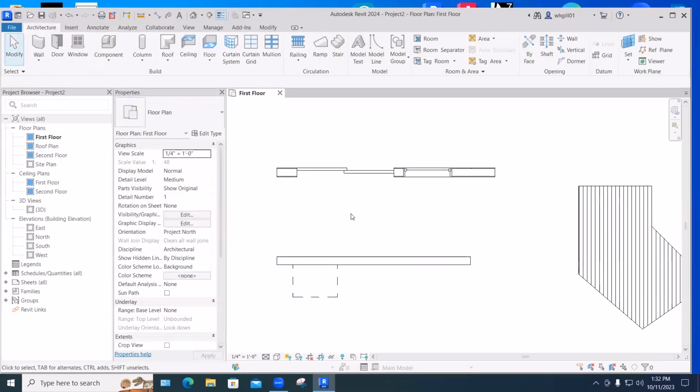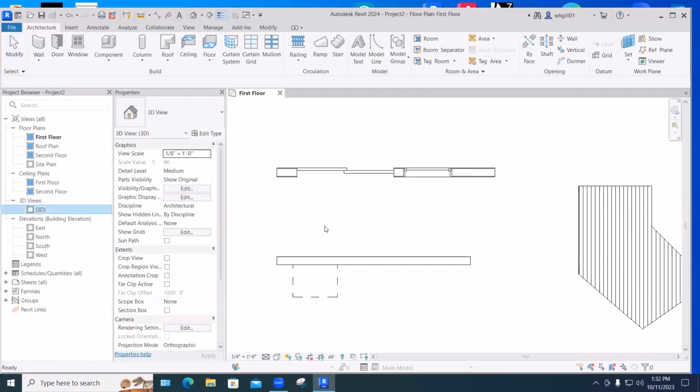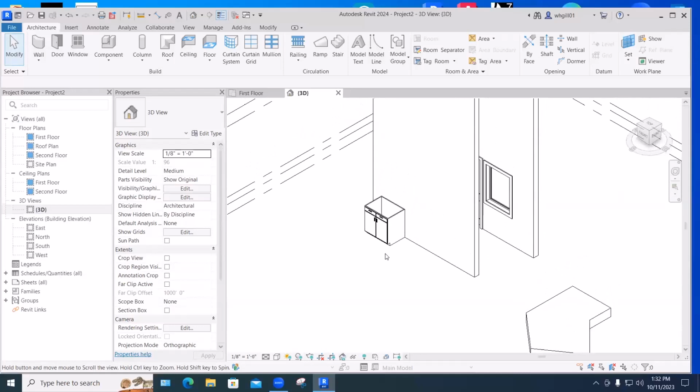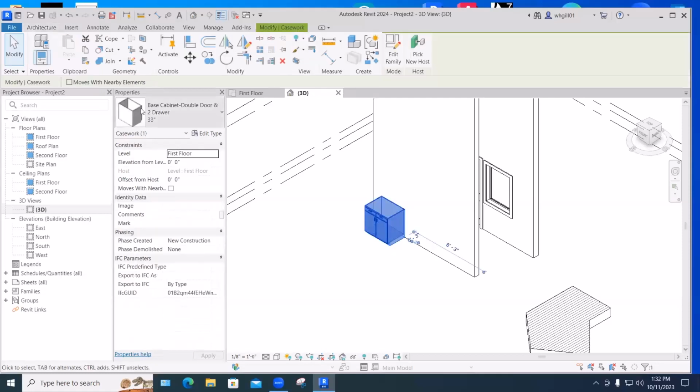And that's showing that way so that when it goes underneath a countertop, we see the dashed lines to know that that's there. If we go into a 3D view, we can see that that's just how it is represented in plan typically. It's actually a true three-dimensional object. Any component that's in the casework category can be replaced by any other piece of casework.